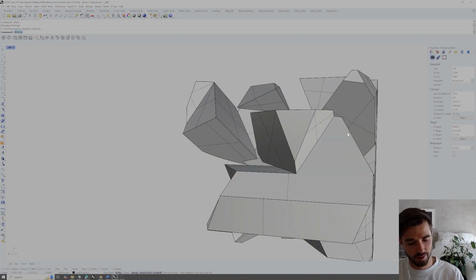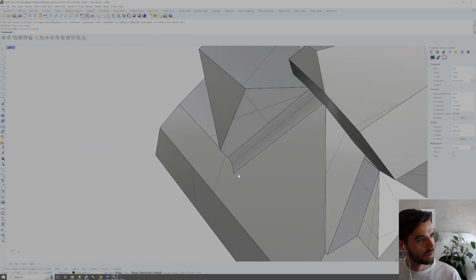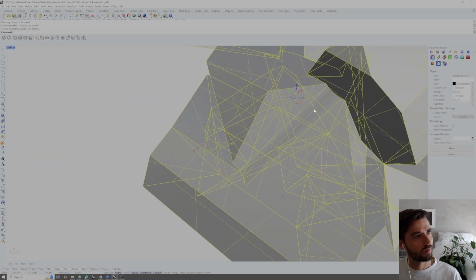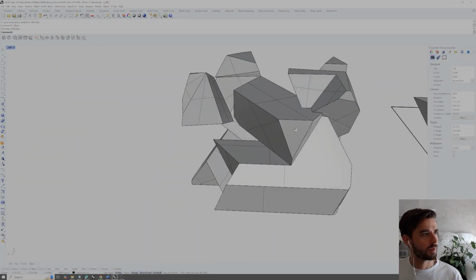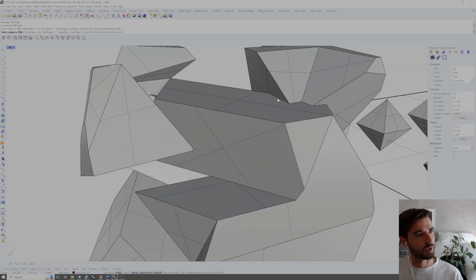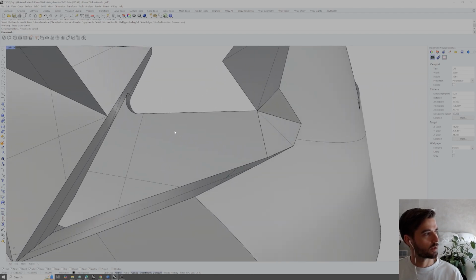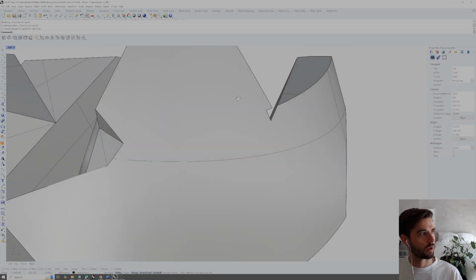Looks like it did not successfully close. Sometimes those kind of sneak by, so it looks like maybe there's some crack or opening here where that piece is not able to close. These tetrahedral geometries are tricky, so you do have to be careful as you're working with them that they are closing and that your poly surface is staying as a closed solid poly surface.